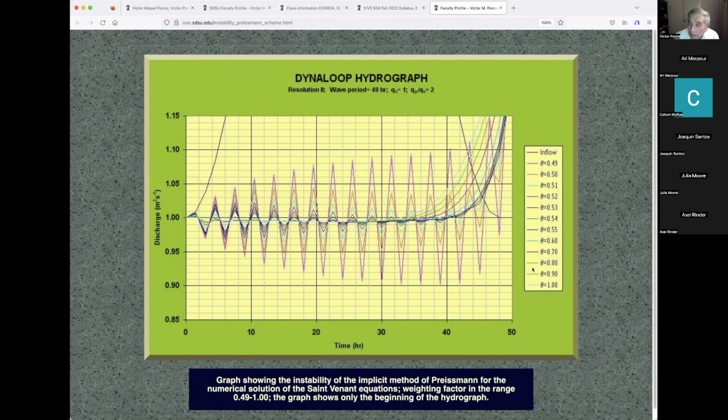So basically what people do in regards to running this model is artificially put in a whole lot of numerical diffusion, meaning numerical dissipation, in order to control the model in these areas here. So they use 0.6, 0.7, 0.8. They can also use 1, but 1 is going to give them a whole lot of diffusion at the peak. They don't want to do that.